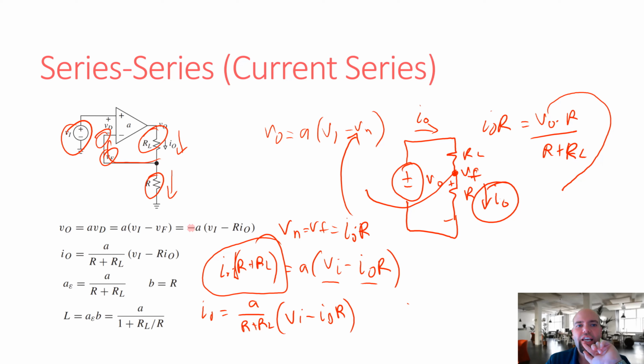In this circuit, if you increased your output load resistance, the op-amp would have to provide a greater V out in order to maintain the same voltage at this terminal, right? It would have to provide a greater V out to keep the current the same, to produce the same voltage across that resistor R.